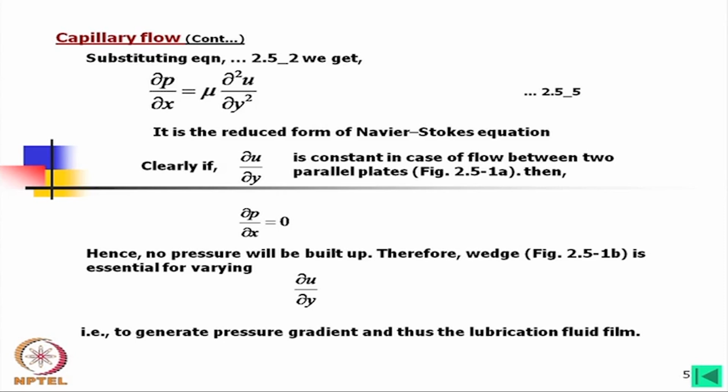Now, I was talking about what might be the problem if there is a rough surface. Apparently, at the top surface some fluid will adhere more to the plate, but due to this roughness there will be breakage in the fluid film; it will be disturbed. But if the plate surfaces have a good finish and the fluid adheres to them, then this fluid film will exist there.